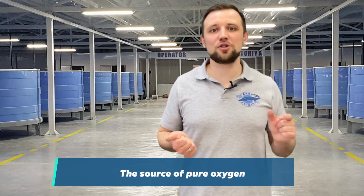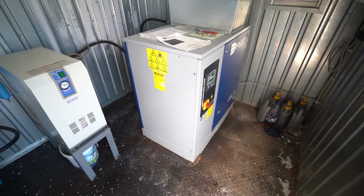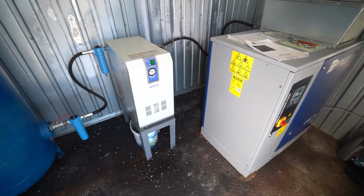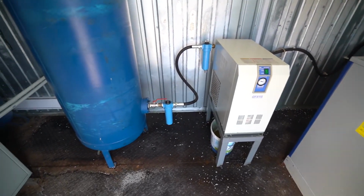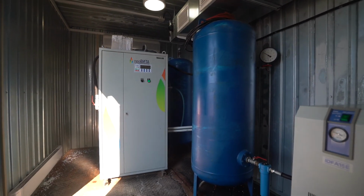Ensure a source of pure oxygen. You need to get oxygen from somewhere to dissolve it in the mixing unit, which is the oxygenator. Where do you get it from? It can be an oxygen concentrator, an oxygenator. Those can be containers with liquefied oxygen. You can use any source. The most important thing is that you can supply oxygen of at least 90% purity. And by the way, at the pressure of at least 1 bar, in case you have pressure oxygenators.